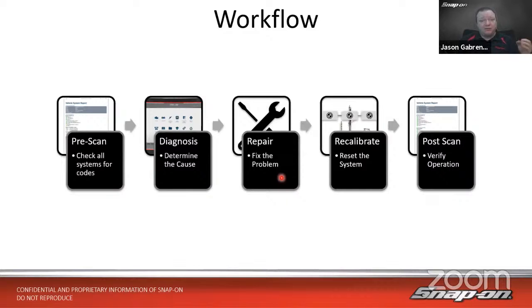Then once the repair is complete, before we do anything else, we want to also check and see, are there any resets, relearns, calibrations needed for this job that I just performed? Because oftentimes nowadays, many components on a vehicle need some sort of a reset, relearn. I replace a throttle body on a car, I need to do a throttle body reset.